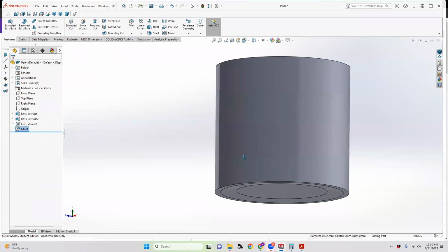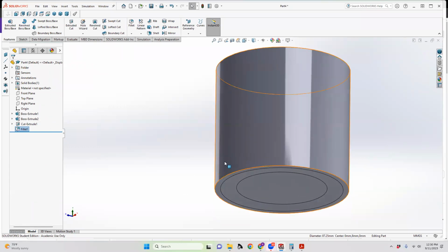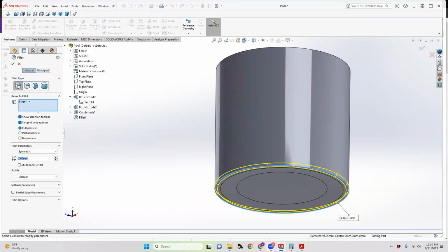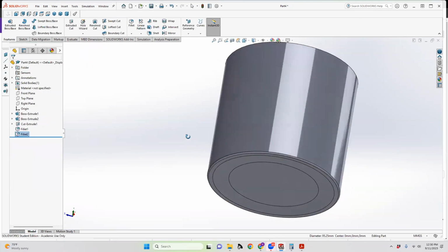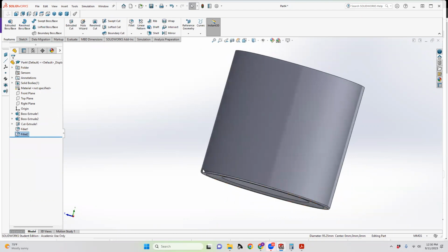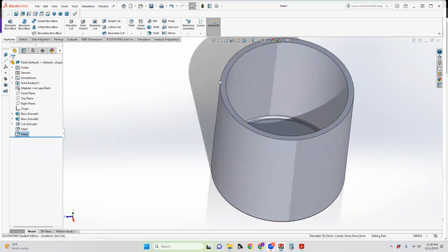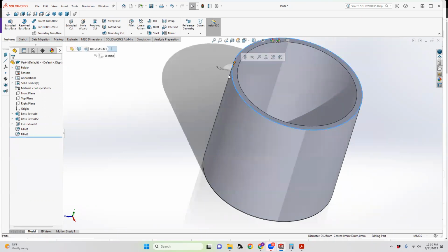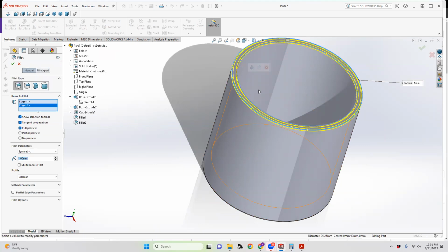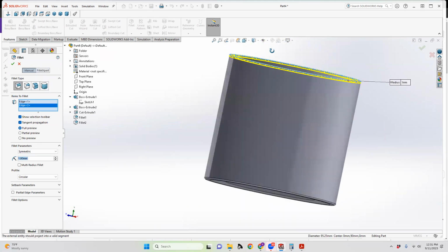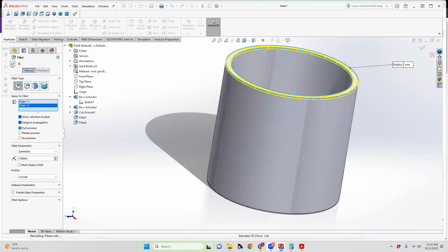Inside. So same deal, that outside edge, we're going to apply the same kind of tool to. So we're going to do a fillet. This one's probably almost always going to be about a 1 millimeter fillet. So it's not going to be very much, but just enough, right? Because there's almost always kind of a smooth edge there. Same thing with the top side. We're going to do our fillet at 1 millimeter. And we're going to do that on the inside again with 1 millimeter. All right.